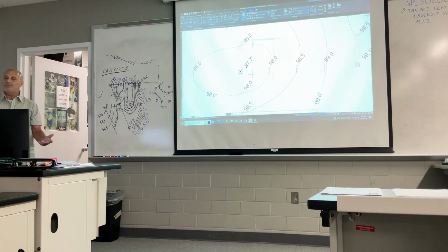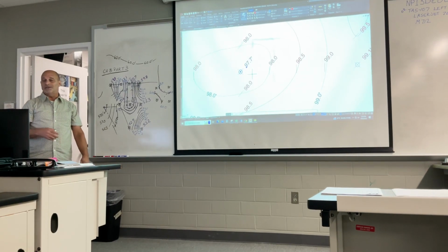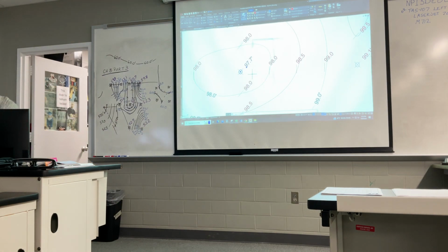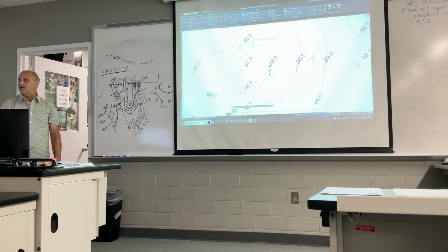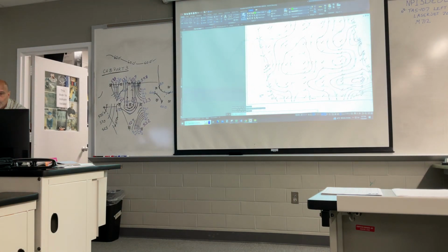They're still on here. I just have them in a no print layer. I said, well, I want to keep those on there, but I want a way of not showing them on this drawing. So I put them in a separate layer that is text hidden or something like that. I call mine ticks, no print layer. So I can look at them, I can utilize that information. Here are my little ticks that I copied from point to point and then went through and put my 6-inch intervals. That is also in a no print layer. The only thing that is printing is my contours with the labels on them.